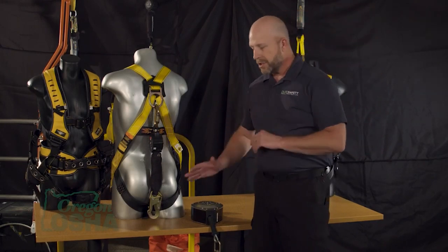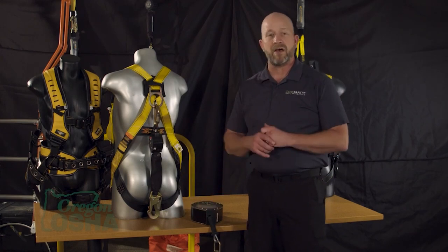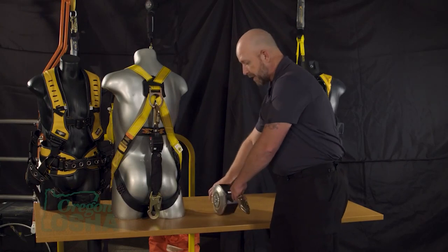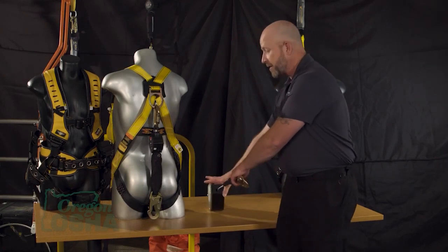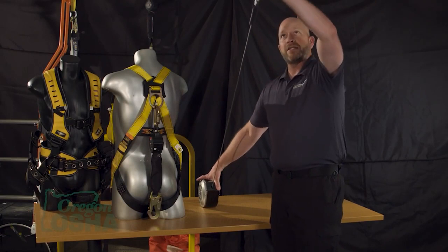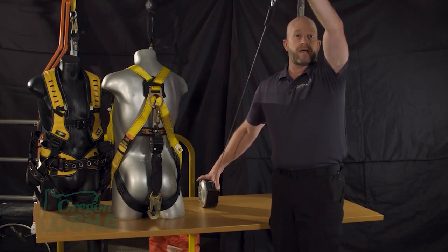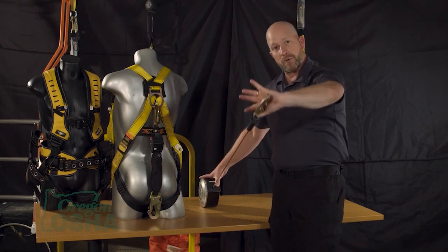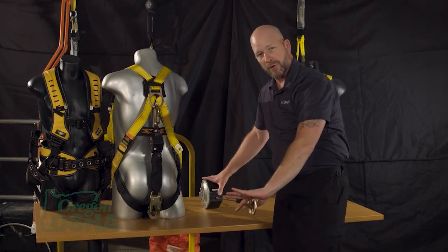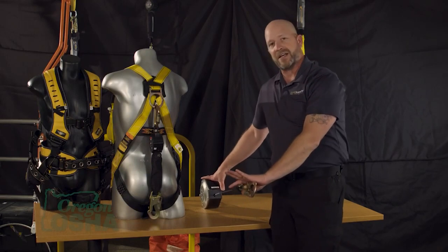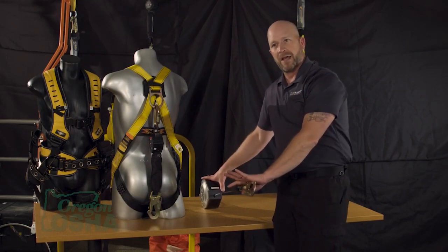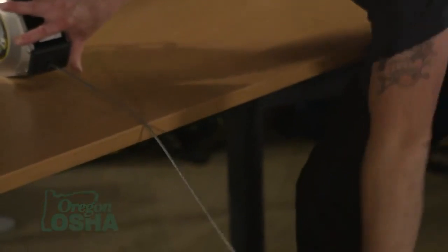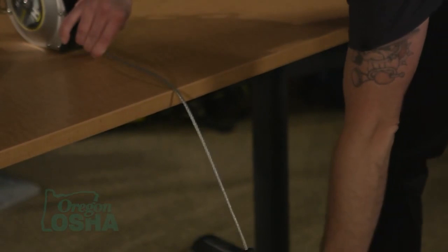And in that case, using a retractable with foot level tie-off being worst case scenario, now we get to a condition where if this is my walking surface, this is attached to an anchor, and now my D-ring is up in the air 5 foot occasionally based off of the worker's height, and then they fall. Because this works like a seat belt, what happens is we're creating acceleration on a device that's not designed to take that. And worst case scenario is as we fall, it will hit this edge